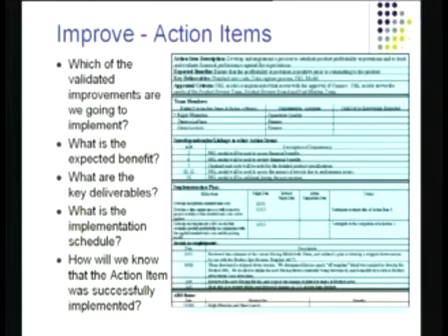We did that Nissan logo falling off problem. There again, we plotted the impact of the various things like glue sticking strength, the thickness of the styrofoam, and so on and so forth. Those things we looked at. The idea was to conduct your DOE and identify the factors that are causing most of the problems in the output. Then we locate also the optimum setting for those factors. So in our case, it turned out glue really did not matter that much, but the adhesion area was a very important one as far as Nissan's logo mounting problem was concerned.